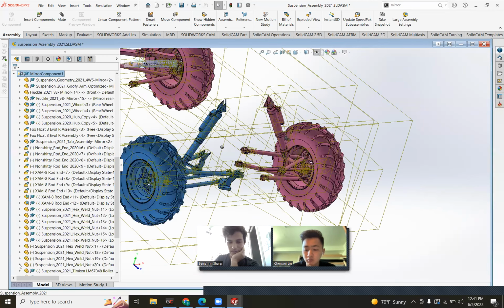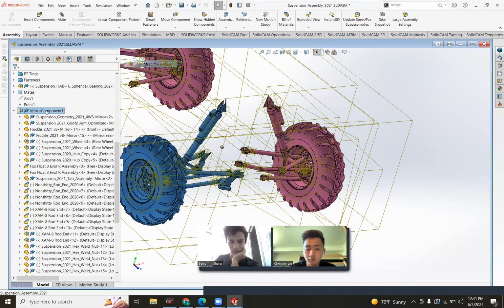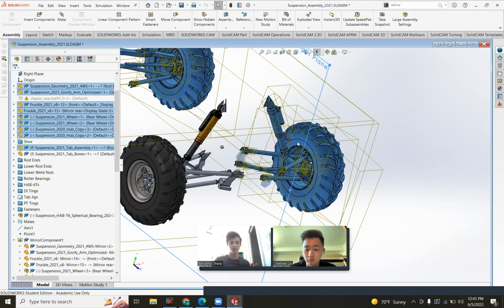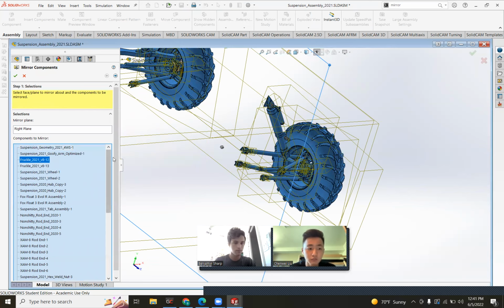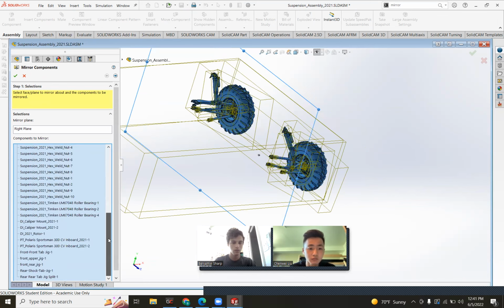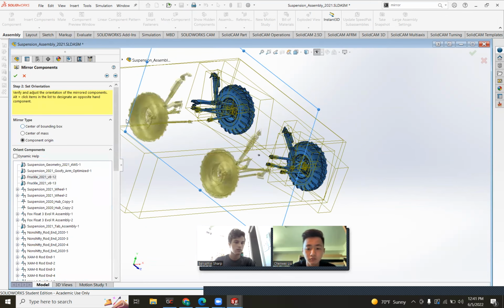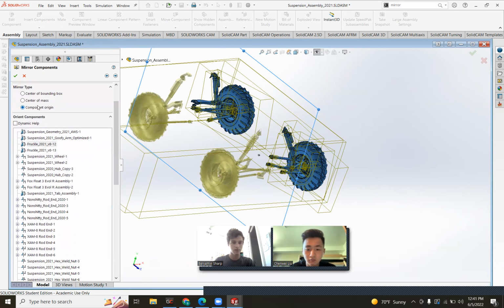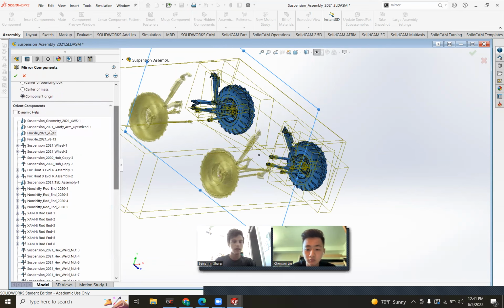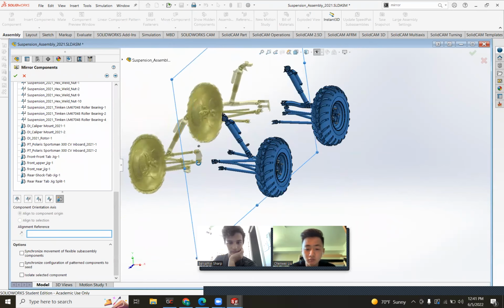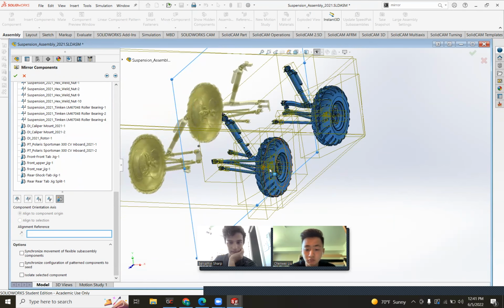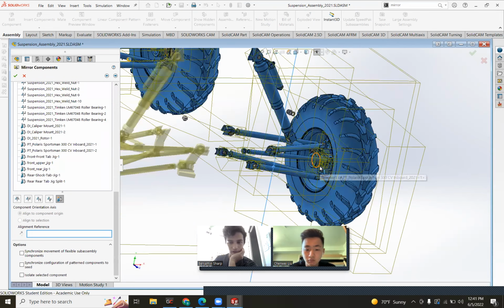What you have to select that isn't the most obvious thing is that for almost every single thing in here, you want to make a left-hand version of the part. So let's say I'm on the knuckle and I want to mirror it around the component origin, doesn't matter. All of these icons right here mean left-hand version, and you choose that down here. Where am I? I'm on the knuckle.